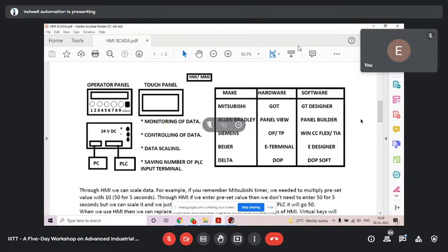You can notice after the session. You can go to Codesys, open the same program and see in ladder. You run your program in ladder. You will see your timer accumulator will show you 1000 for 1 second, because one second has 1000 milliseconds, right? So that ladder or PLC is showing you time in milliseconds.